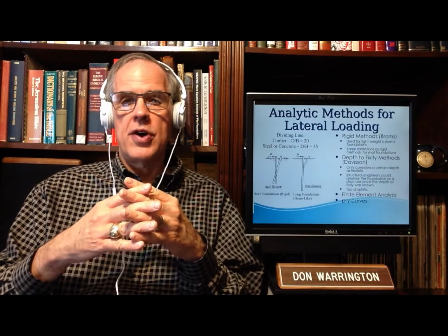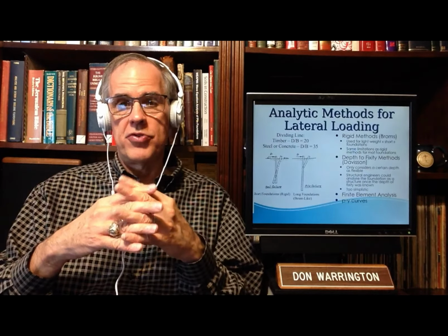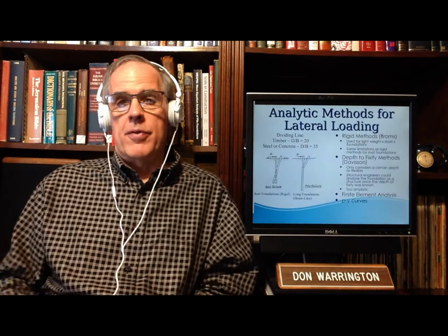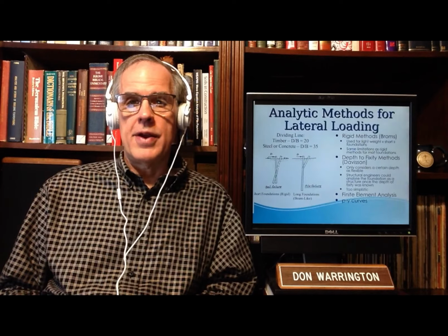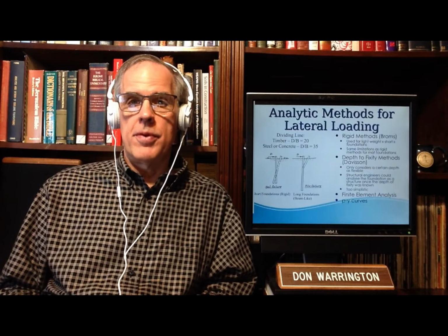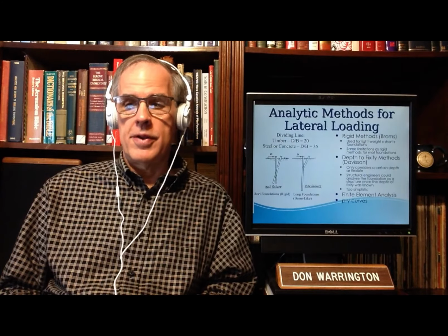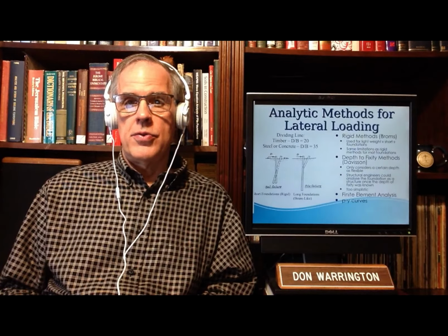The pile was okay with it. It was the soil that could not be modeled with Winkler methods or any other kind of linear methods. So we had to turn to nonlinear methods, and ultimately from a math standpoint, to numerical methods, either FEA or finite difference, like your PY curve methods, to solve this problem.